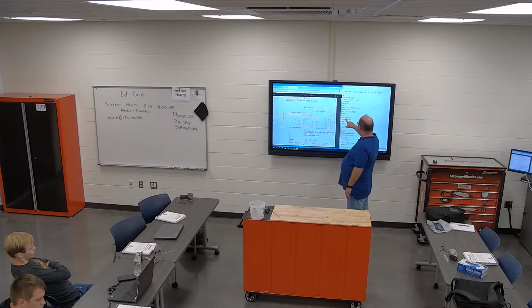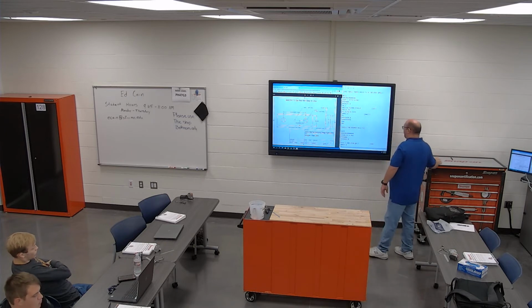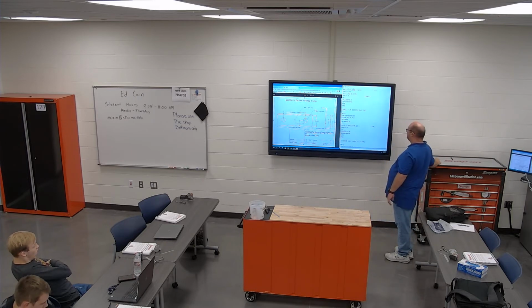M5, G91, G28, Z0, G28. You guys know what those are. So this takes your spindle home. This takes your table home. G90, M1.